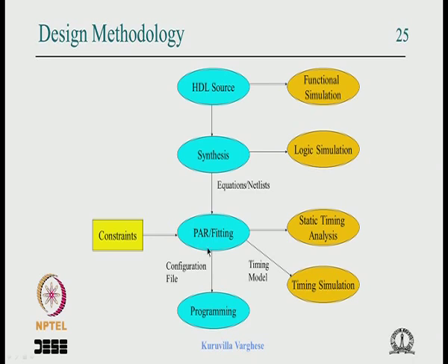Ultimately some kind of a printed circuit board has to be used to mount this FPGA, so that can go parallel. So these IO pin assignments are specified in the constraints, and another thing which can be specified is, as I said, the placement, which is a very critical and complex thing to do.